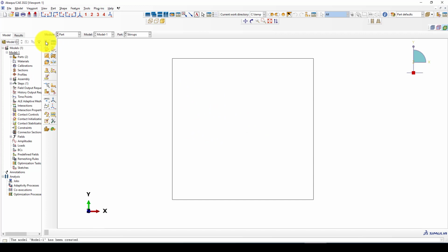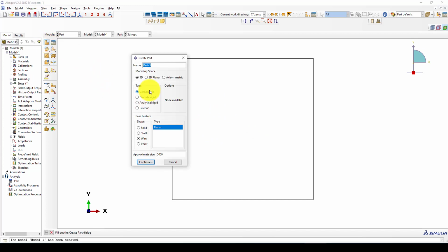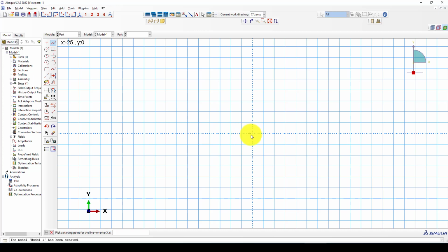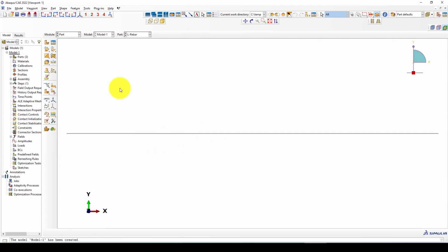The strap is also constructed, and the second is called longitudinal rebars or rebar. This is also a wire, and I want to give it 2 meters, or 2000 millimeters. Now this is also completed, and the next part is defining material.